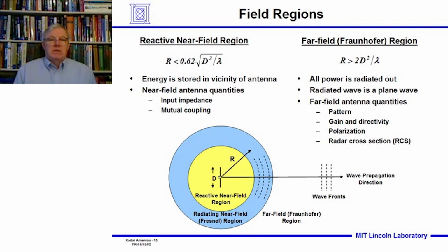What that really means is that the waves which come out from the antenna as spherical, by the time they get to you, can be superbly approximated as plane waves. Under those conditions, that's called the far field, and this is the algebraic condition for when that's true. If the range is greater than twice the antenna size squared divided by the wavelength, then you're in the far field. And this dude Fraunhofer did a lot of the calculations. That's the far field region.